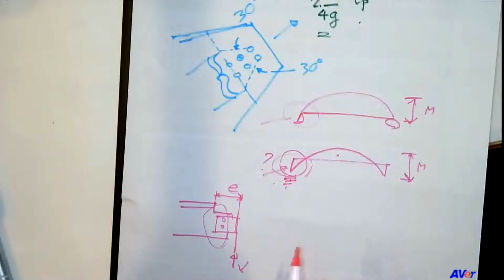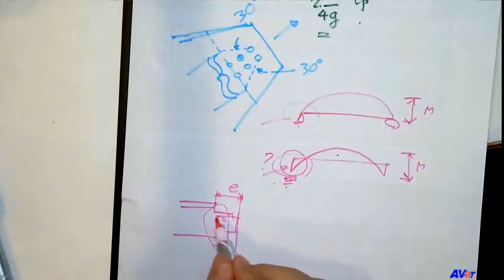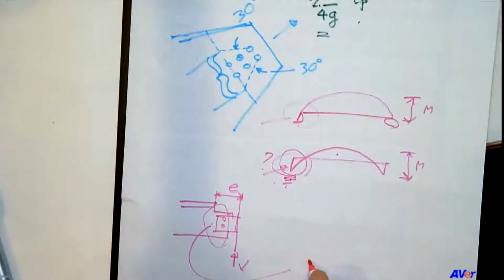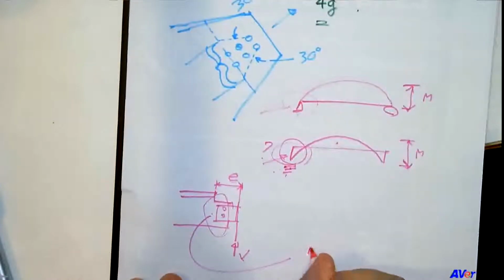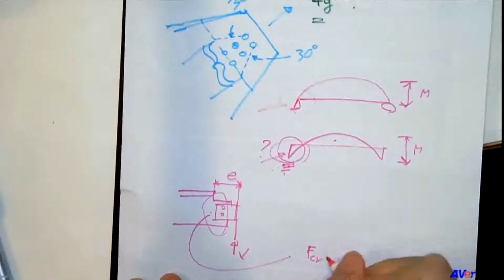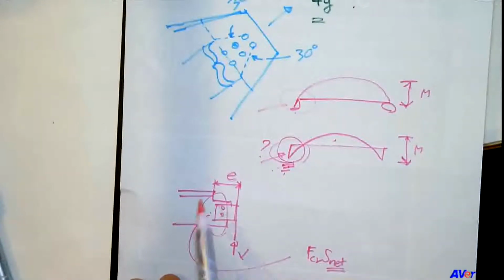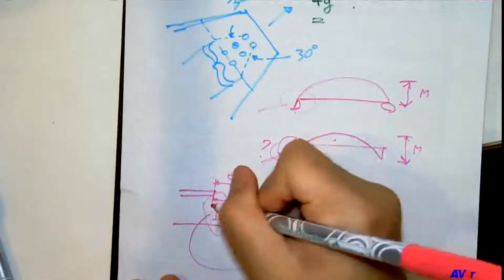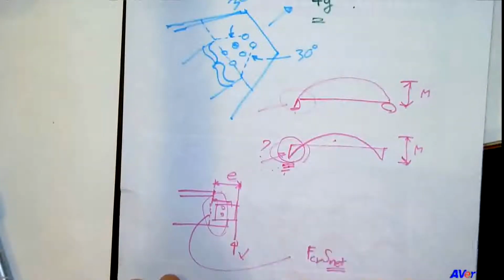And then we will check the moment capacity of this portion from the formula shown in the slide, that is the F critical multiplied by the elastic section modulus of the net section, because we need to remove that, right? So you need to recalculate the moment of inertia of this section here, and then calculate the elastic section modulus, okay?